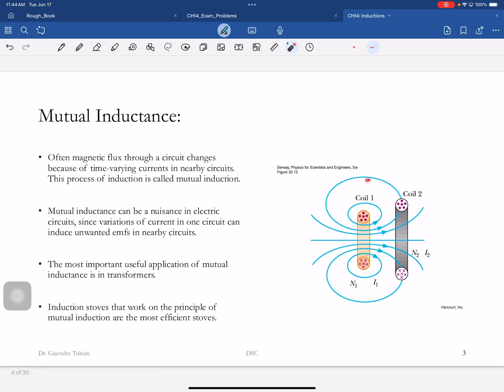So here we go. So here is a coil. I'm going to feed an AC current through this coil, and the current is producing this magnetic field. If I pass an AC current through this coil, this magnetic field changes and it induces a current in this coil. What happens if I pass a DC current through this coil? Magnetic field is constant. And there won't be any induced EMF in here. Okay, so what we want is a change in currents fed in here that'll induce a voltage there.